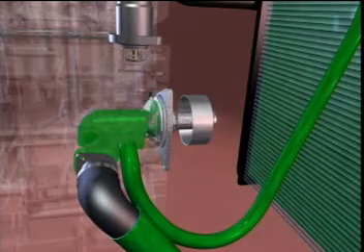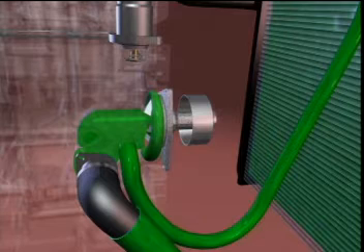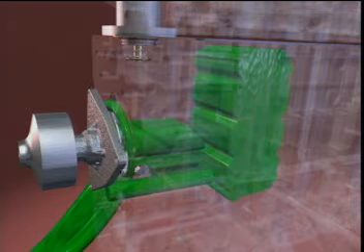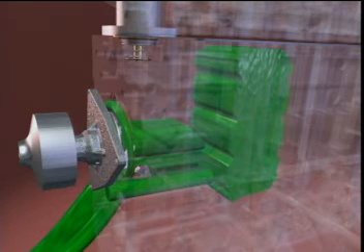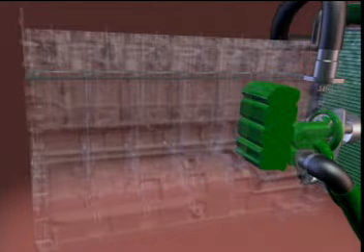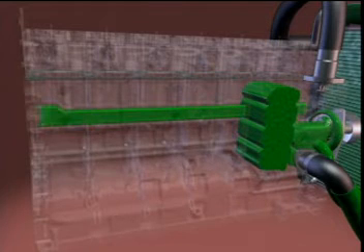Coolant is circulated by the integrally mounted water pump. The output from the water pump empties into the oil cooler cavity of the cylinder block. This provides the oil cooler with the coolest possible coolant. From the oil cooler cavity, the coolant flows into the lower water manifold.